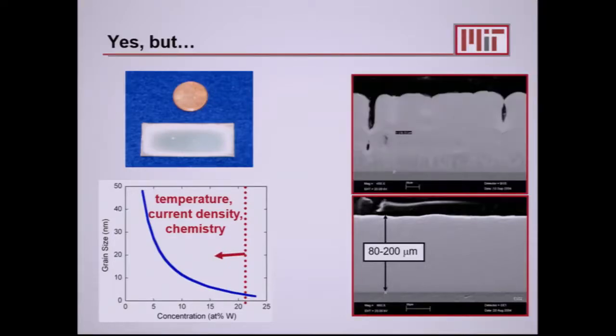And if I try to walk away from the sweet spot, I get coatings that look crummy, okay? So first of all, they might have voids or crevices or cracks. And maybe you can see this, maybe you can't, but if you squint, you might see there's even macro segregation here, right? So we're not even properly forming an alloy. We're getting segregation as the thing is trying to grow. And so these are really crummy. The only way I get a good coating is to stay right here in this sweet spot.